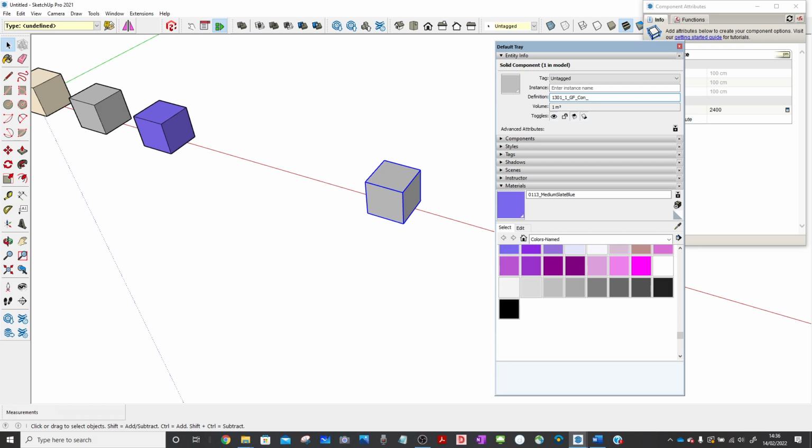This part we can call floor slab. And then you may have more than one floor slab in your structure, because you can't just pour vast masses of concrete all in one pour, or you'll have cracking. So we'll assume that it's just one pour just now, but be mindful that in real life you would have to break that up. So we'll call it underscore 001.